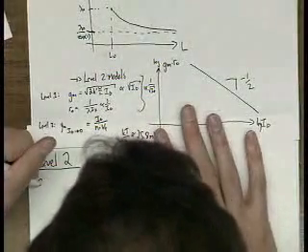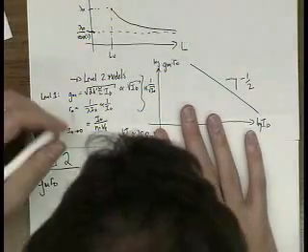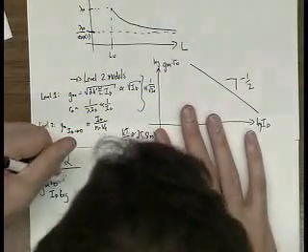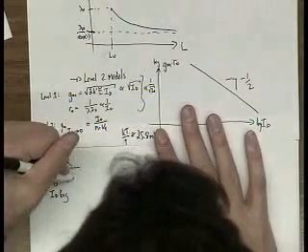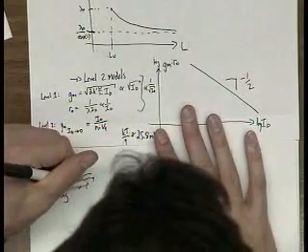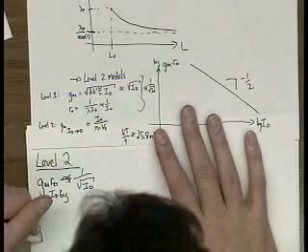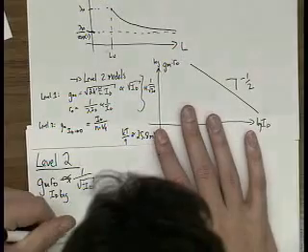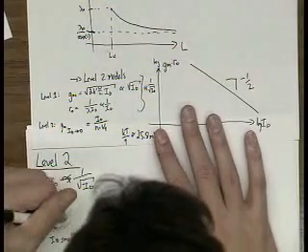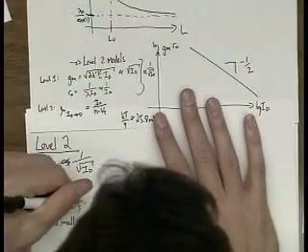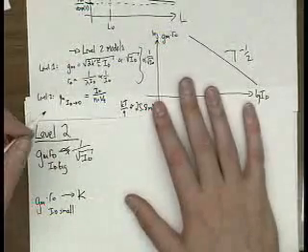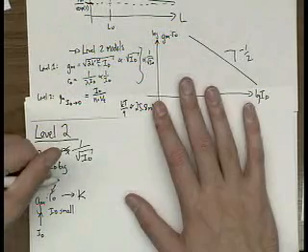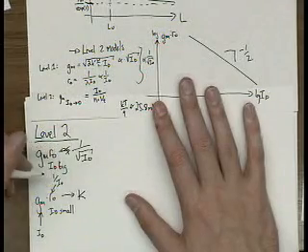Level 2, GM R out for ID big looks like square law, so it's proportional to 1 over root ID. But GM times R out for ID small becomes a constant, because GM is proportional to ID, and R out becomes proportional to 1 over ID.